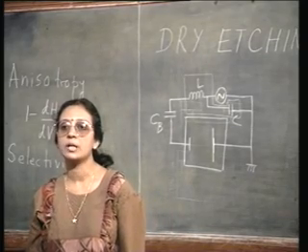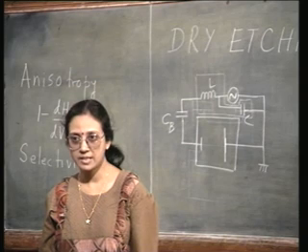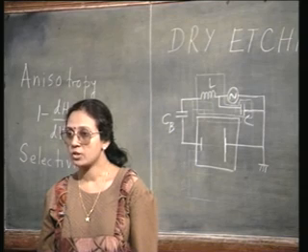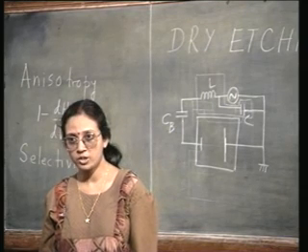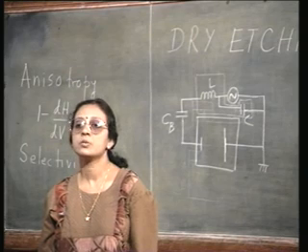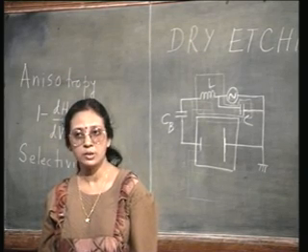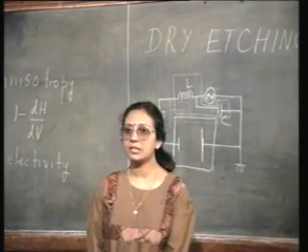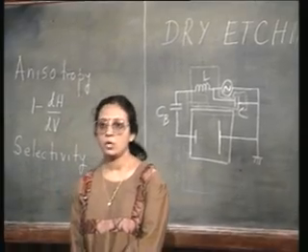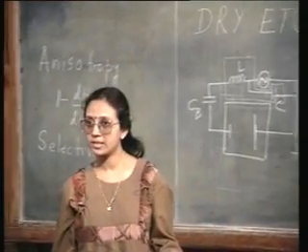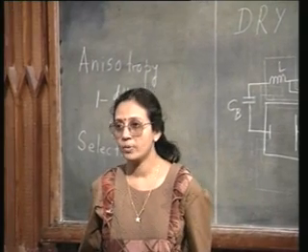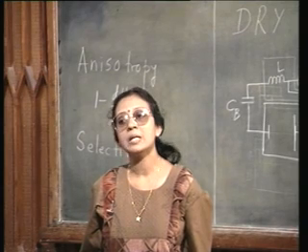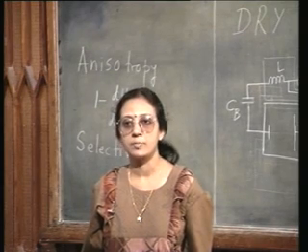In addition to that, we can reduce the pressure inside the chamber, and then in order to sustain the plasma, the electrons must have higher energy and therefore higher potential, or we can even reduce the frequency to a certain extent to increase the sheath potential. And the potential difference between any 2 points will actually determine the electric field strength, and consequently that will determine the ion bombardment energy. So, it is very important where you place your substrate.